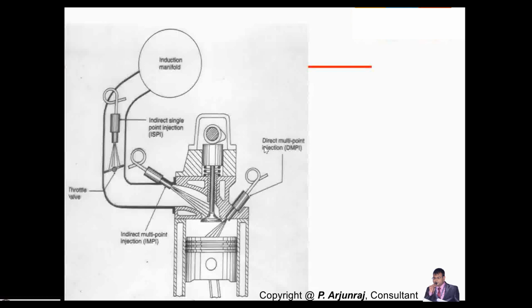Strictly speaking, even if it is a multi-cylinder engine, we apply gasoline direct injection considering the multi-point injection system, where the injector will inject fuel into the combustion chamber directly, and you get the advantage of emissions, power output, and acceleration.